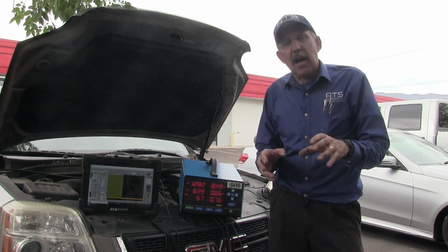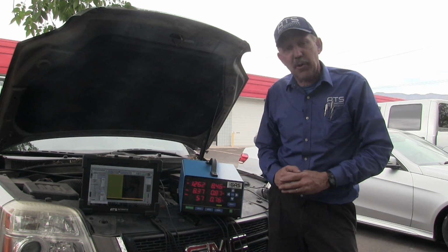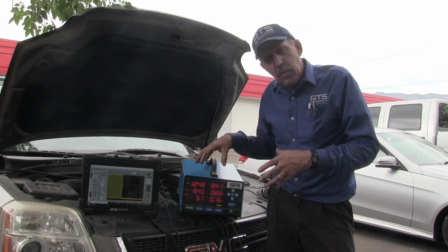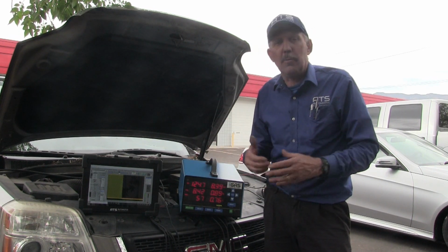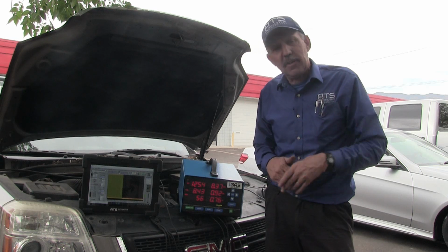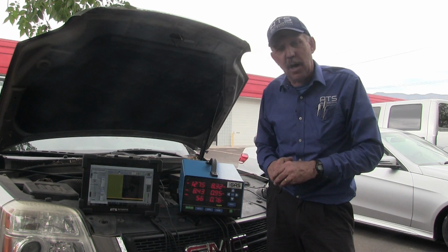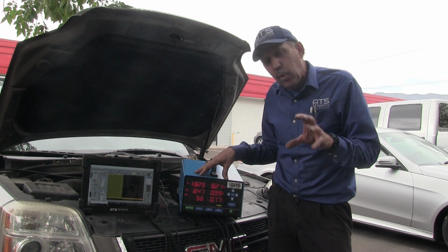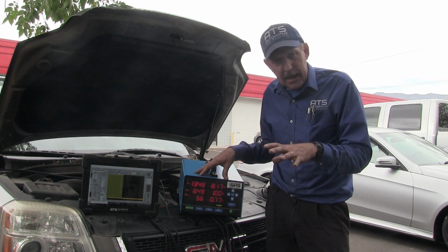So you guys that got gas analyzers, get them out and use them for diagnostics. This tool wasn't made as an emissions tool. This tool is made as a diagnostic tool. It was made in the 50s. Back in the 50s, no one was worried about tailpipe exhaust. They were worried about how you fix cars. And a 5 gas is a great way to test the feedback circuit.